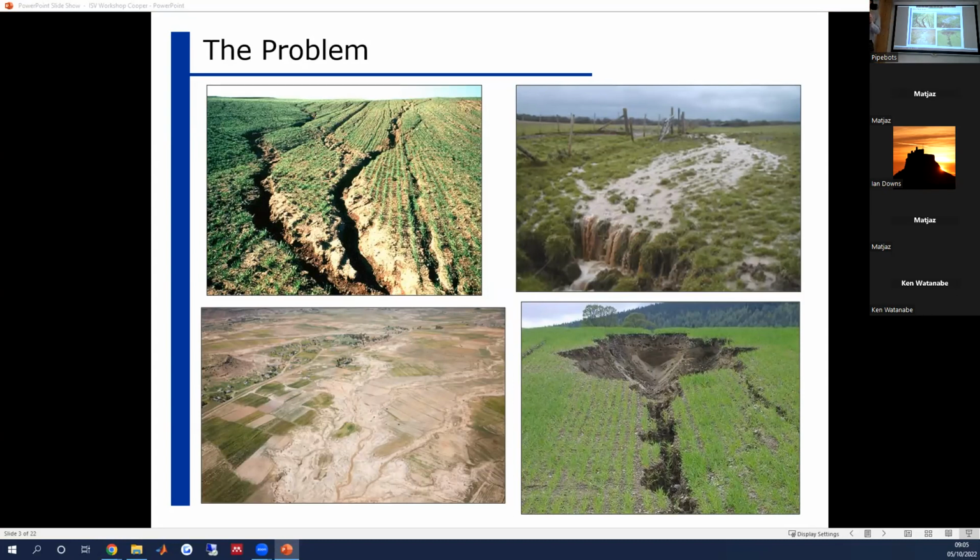The tricky thing is how to go about measuring those dynamics. You can't put an instrument in the flow itself, because of course it disturbs the flow and causes local scour. So you can't use something like an ADV. But the issue is actually making sure you're able to capture that event.